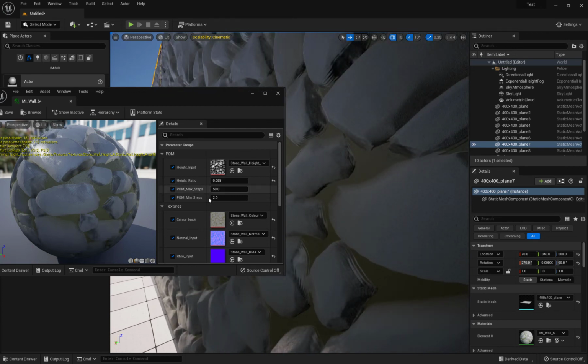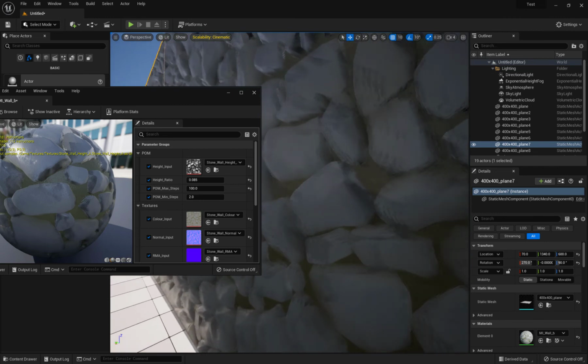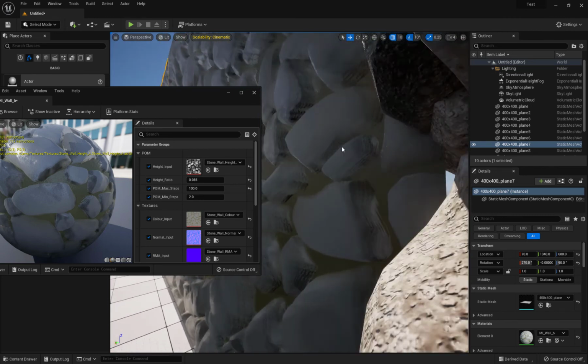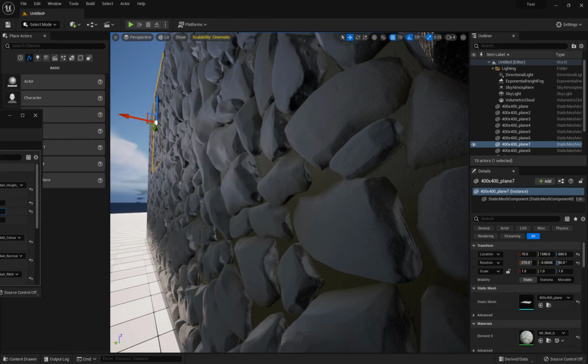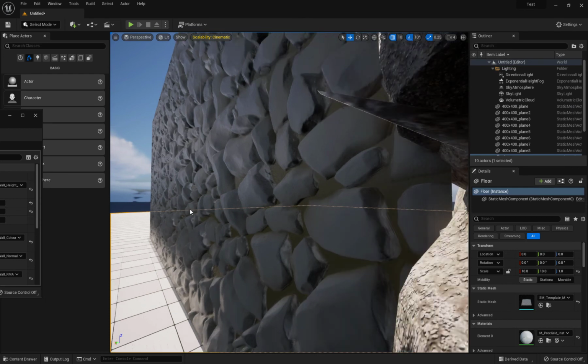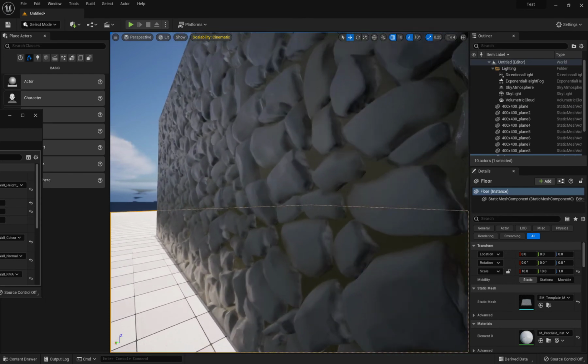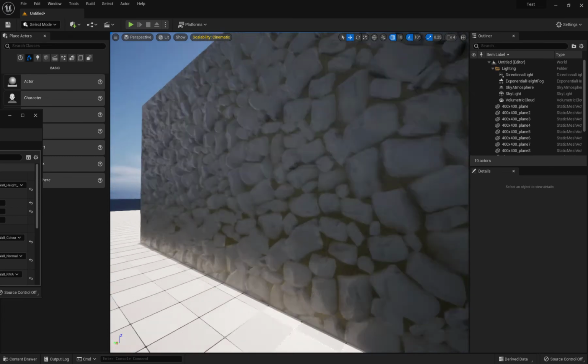When you get in, you see how that's stepping up. So we might want to increase the steps here, like to 100. Give it a minute. And then that's a little bit better. But the more steps we have, the more expensive this is. You can see there's less stepping now. If I'm standing here, that wall looks as though it's three-dimensional, with all that lovely lumpy bumpy stuff.